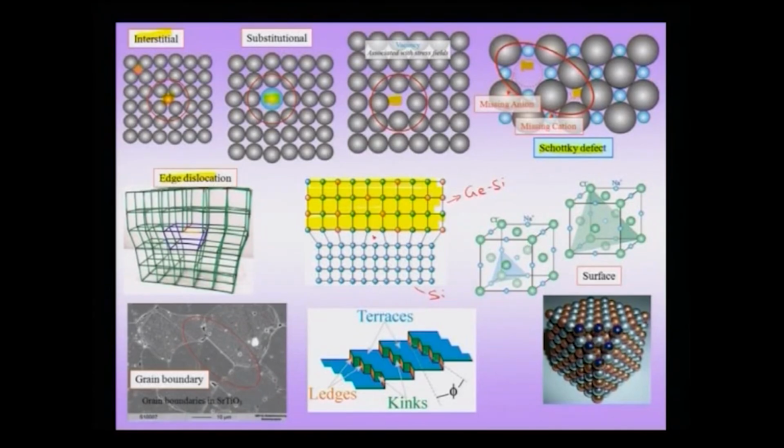The dislocation which is present between the two materials can be thought of as an interfacial misfit dislocation. In some sense an interfacial misfit dislocation belongs to the class of structural defects and not to a random defect, because now it is localized to this interface between GeSi and Si. So, an interfacial misfit dislocation is a structural dislocation, unlike the random dislocation, which is the one shown on the left hand diagram.